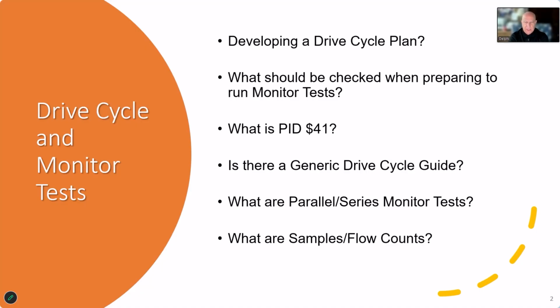This is a hidden gem. When it works, and it's not that the system, the way it was designed, works well, it's how it's handled within the scan tool. I'm going to show you some examples of that because that can be a time saver for you too, especially if you don't want to clear existing readiness and maybe you've had a DTC and you want to drive it out. This is the way to do it.